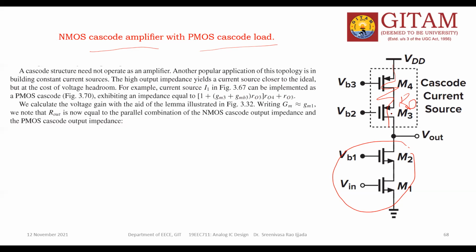Because of fabrication difficulties, space difficulties, a lot of things are there. And moreover, there is an issue of the accuracy of the particular resistor value. So to nullify all these issues, in place of RD we can keep a transistor, which must be operating in saturation. That's why in place of RD, I again kept transistors, but this time PMOS transistors.